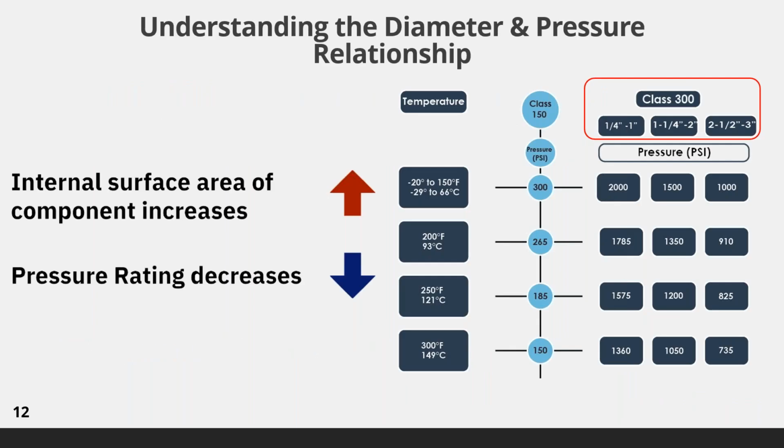Class 300 fittings pressure rating charts have reduced pressures for different nominal sizes. For example, a 1-inch fitting is rated at 2000 psi, double the rating for a 3-inch fitting at the same temperature. Pressure rating reductions for larger ball valves is also the norm. For example, our 0827 series ball valves are described as a 600 CWP rated valve. However, you will see a notation indicating that the 2.5-inch and larger valves are rated at a lower 400 CWP rating.